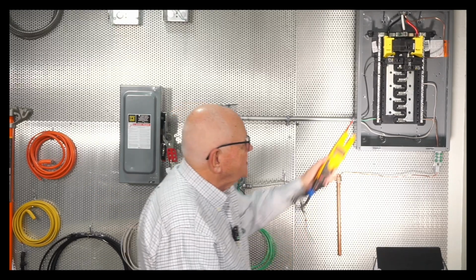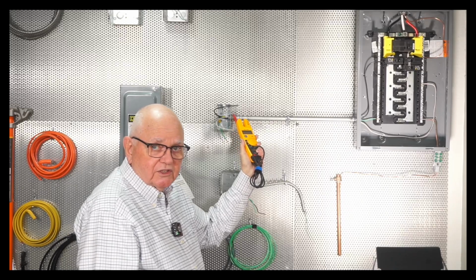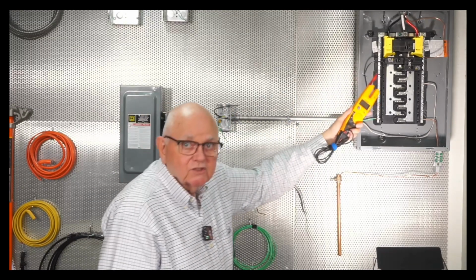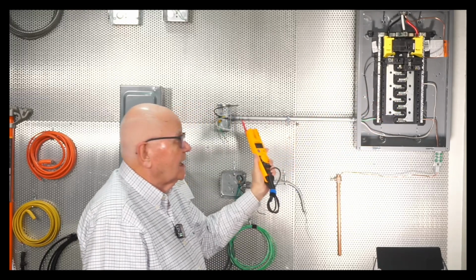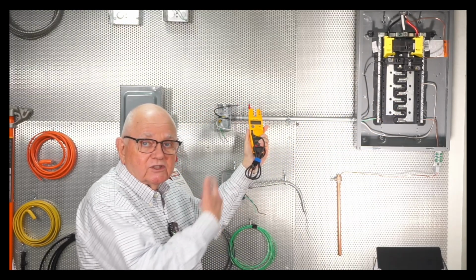The branch circuit is the conductors. It doesn't say that the branch circuit includes the overcurrent device. The branch circuit is the conductors that run from my overcurrent protection in the circuit out to where I'm going to utilize the electricity. Final overcurrent protective device, the conductors from the final overcurrent protective device out to where I'm going to plug or attach something out here and eventually utilize that electricity with some utilization equipment.